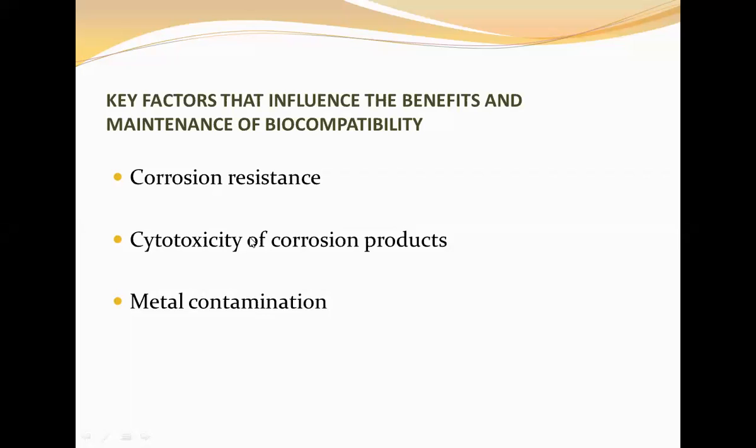That is why we use titanium, because its byproduct is even more biocompatible than its original metal form. So the cytotoxicity of your corrosion products is very, very important. If your corrosive byproduct is cytotoxic, we never choose that particular metal.